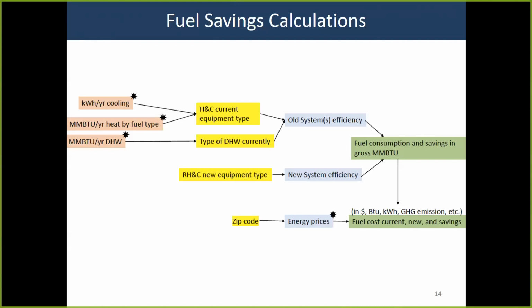I don't think there's enough data out there yet to really vary this by, say, heating degree day bin, but we at least do have a Northeast regional number, and Massachusetts does sit in a kind of moderate or average New England area that can provide a decent starting point for this number. A lot of the existing system efficiencies are from the EIA Annual Energy Outlook, and it's not a projected number, but it is their 2017 residential efficiency, so that we're trying to provide consistent assumptions that can apply.